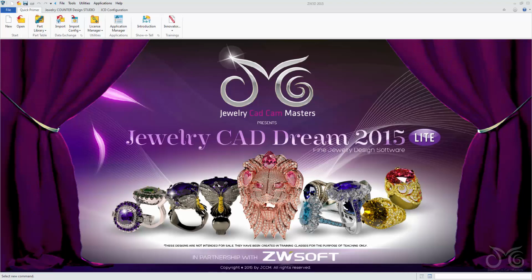Okay, so in this class we're going to be introducing our gemstones. We're going to be placing some gemstones, and we'll see that these come in as a component entity, and we'll be looking at what a component is. We'll also be taking a look at the extrude command in the shape ribbon tab, and then we'll be using the extrude to create a basic bezel setting for our gemstone.